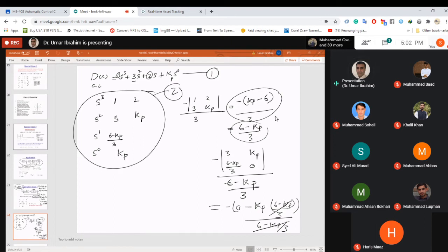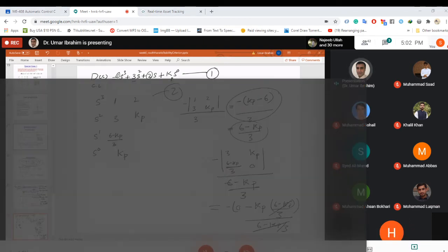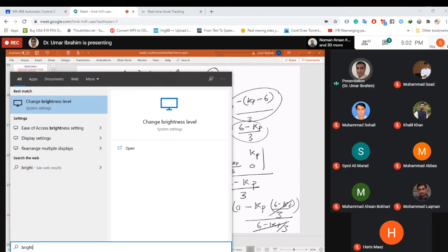Step 2 of the Routh stability analysis. Okay. Next, let's interpret, step 3 of the Routh stability table. Of course, in the previous case we didn't have any variable. In this case, 2 of the 4 values in the first column have a variable. But we are not interested in the actual value.